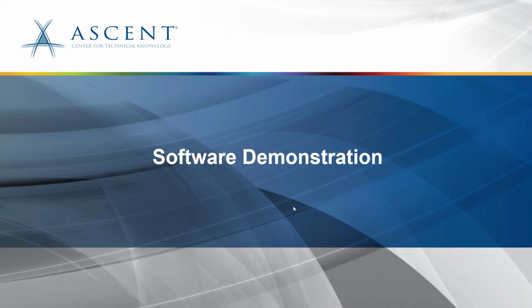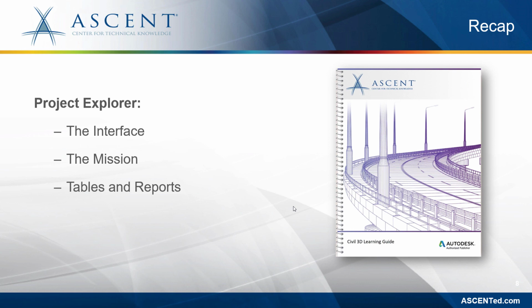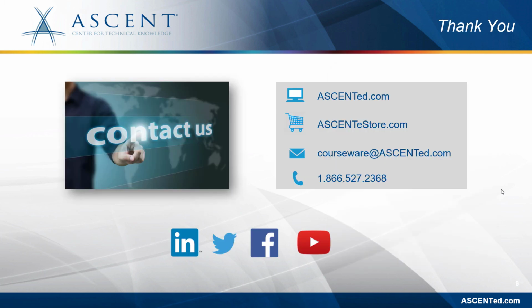And back to PowerPoint. So we looked at the Project Explorer, we looked at the interface and the various components thereof. We went into Project Explorer and actually solved some of the issues we had for the storm sewers. One of the head walls was actually underground, and the other, we changed the slopes for a better runoff. And we looked at tables and reports within the Project Explorer.